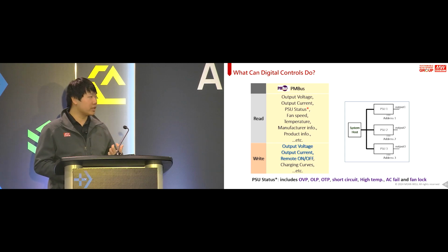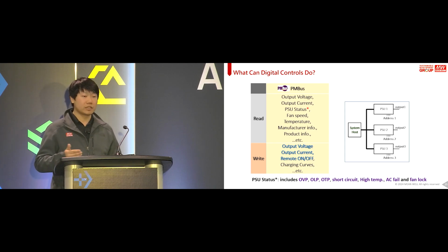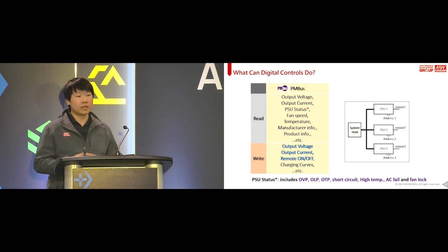And this is especially important and creative for applications that can do preventative maintenance. They can monitor the fan speed of the power supply. If over time they track that the fan speed is increasing, that means the internal components may be degrading and failing. So they can set certain thresholds. If the fan speed gets to a certain point, they can perform maintenance on the power supplies, or swap them out.